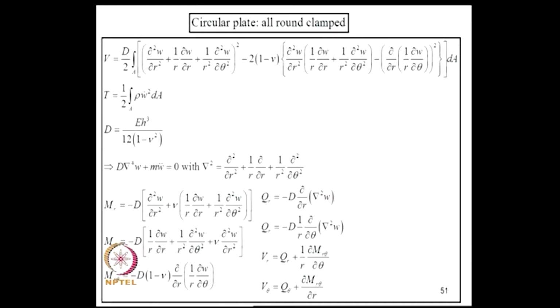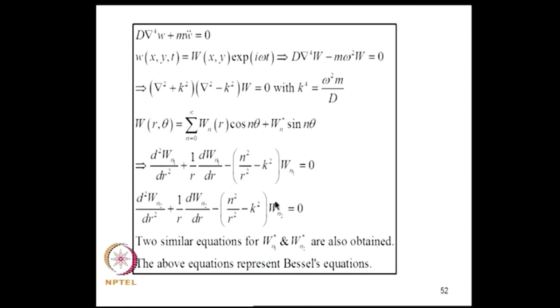Now, circular plates are another class of problems which are extensively studied in the monograph by Leissa, and for that the strain energy expression in the cylindrical polar coordinates, the governing equations and stress resultants are reproduced in this view graph. This is for the sake of completeness. Now, again here if we assume for free vibration analysis all points on the structure vibrate harmonically, the eigenvalue problem will mathematically be of this form, but this del square operator will be now quite different.